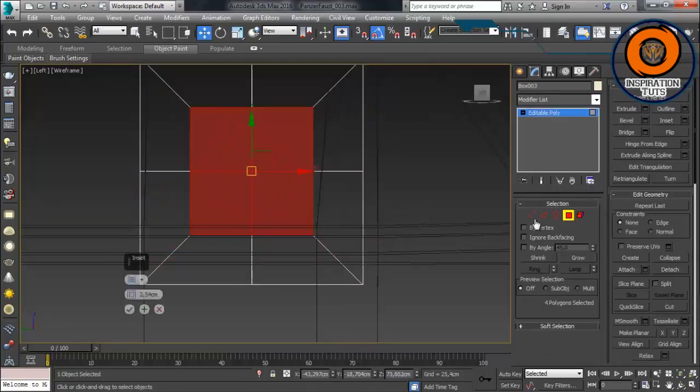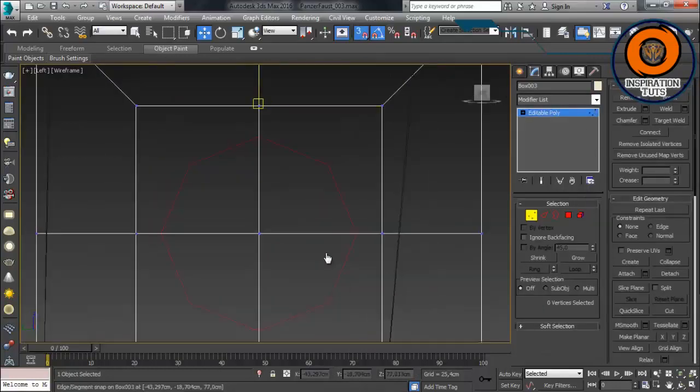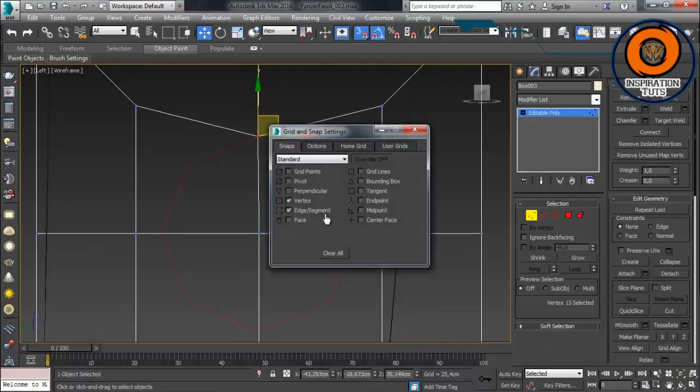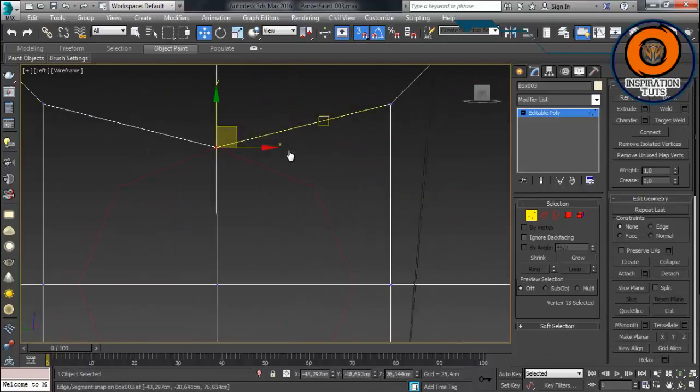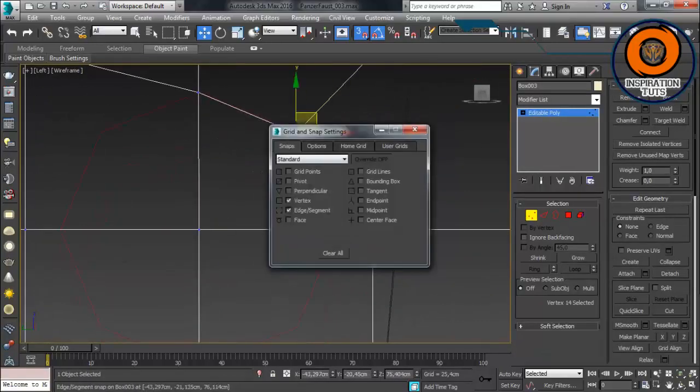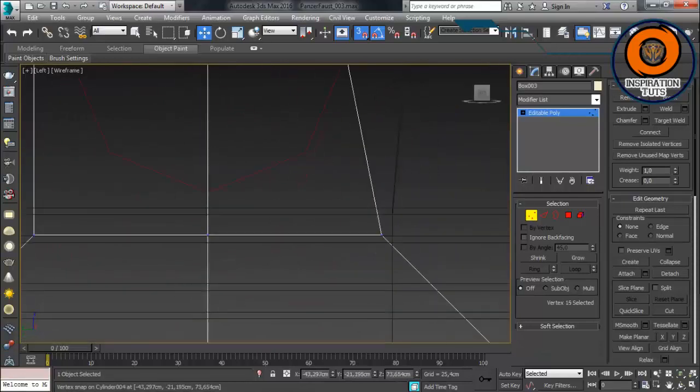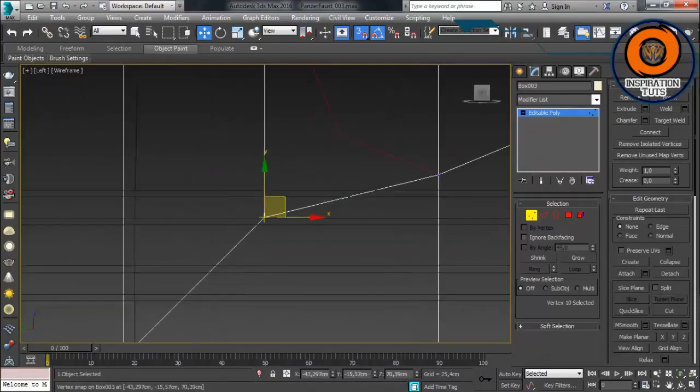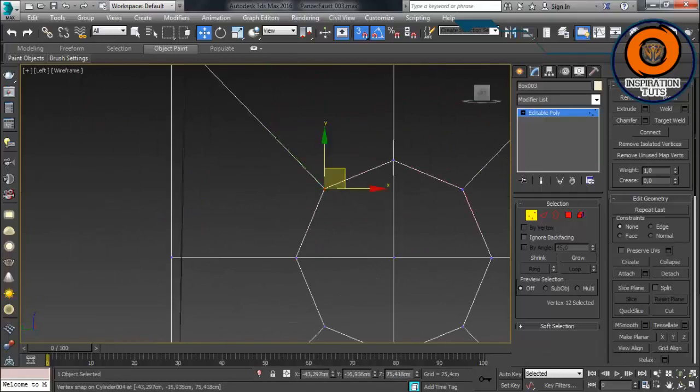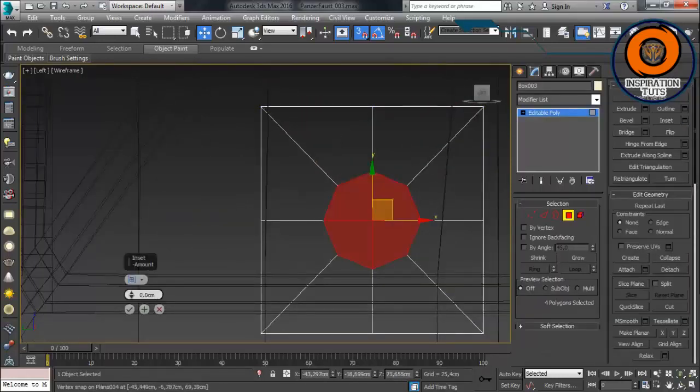After that, we're gonna use the method we've used all the time, which is just to use a cylinder, and after that align the vertices of the circular selection we've created to the edges of it, or to the vertices that compose the cylinder, just to help us get something straight and clean.